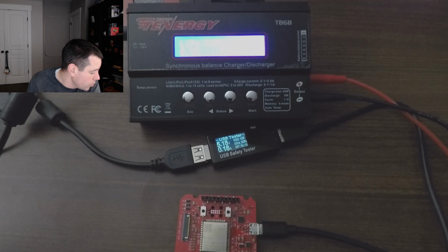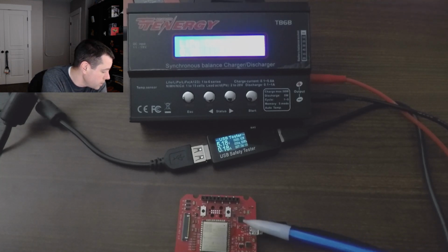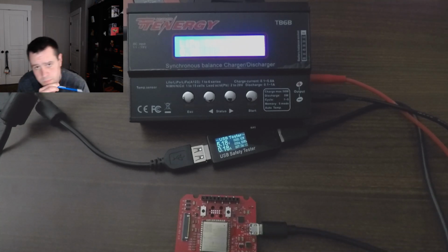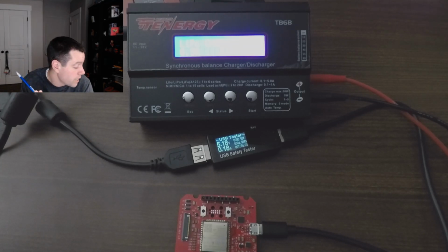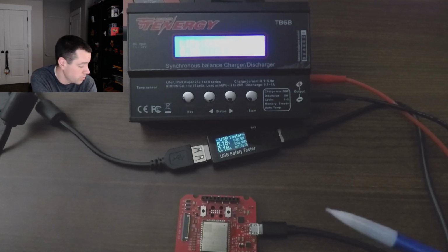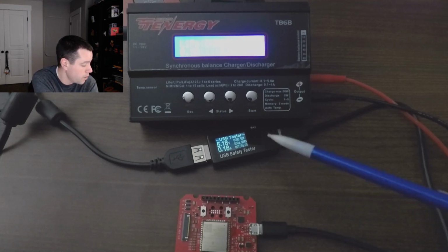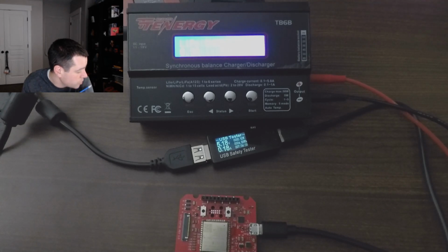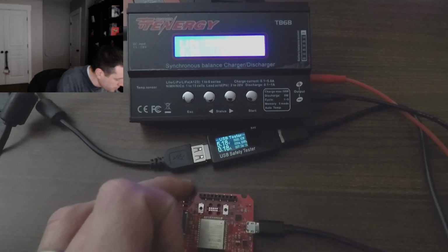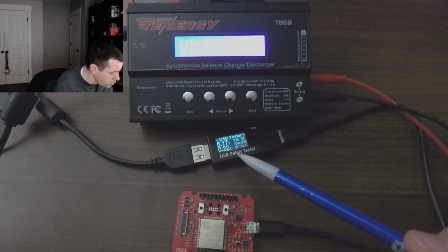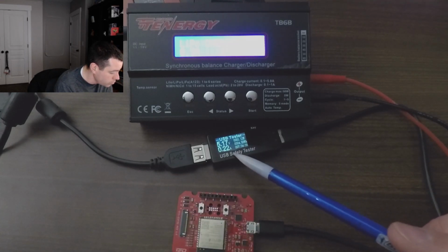And I know that this guy right here, the FTDI chip, consumes about 8 to 9 milliamps when it's active. It won't be active in this configuration because it's not negotiating with a host. There's no data lines connected inside of this cable right here. It's just a straight power connection. But interesting. I'm going to hit the reset button. Let's just watch it again. See what happens. Reset. Goes up to 220. So I'm using 40 milliamps to do something.